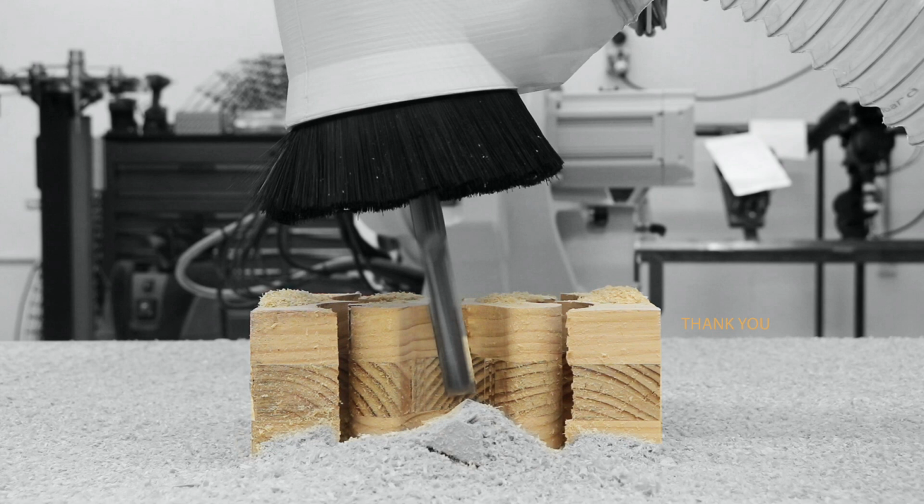The simpler the design, the faster the cutting time and the cleaner the cut, meaning the right fit is more achievable and assembly is far easier. The use of a wedge shape to complete the connection means fabrication is not as simple, but it creates a much stronger joint that is less reliant on it being the perfect fit, as the wedge creates friction that pulls the pieces together. The process also highlighted the importance of working with the machinery.